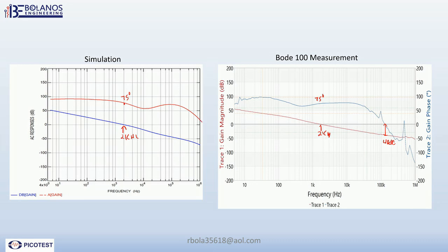Here it's a little bit off, but I'm okay with this because it's a simulation. I have a measurement. The measurement backs my assessment that the power supply is stable. So this is the way you measure, and you get both simulation and measurement. And with these two coming very close to an agreement, then you can have confidence that your power supply is going to be stable.